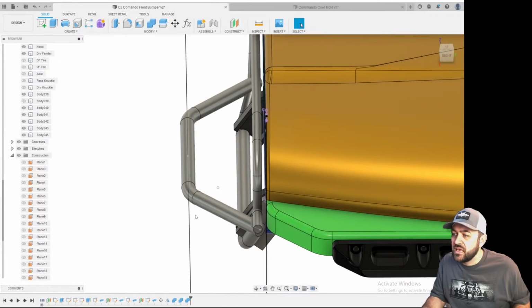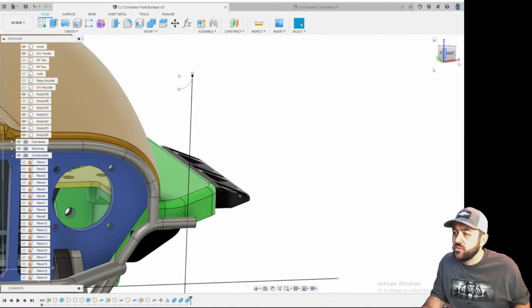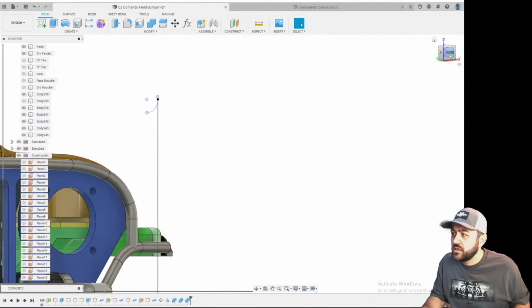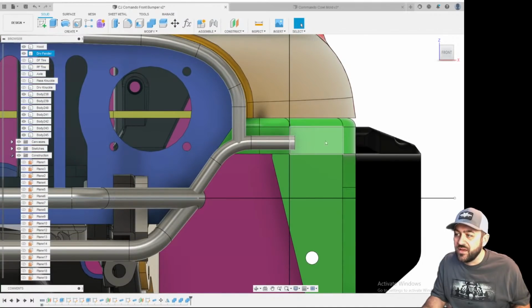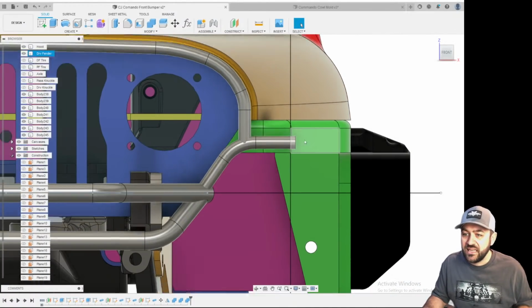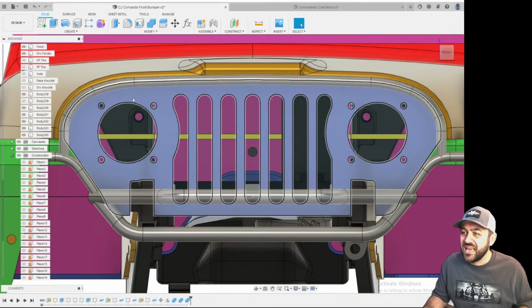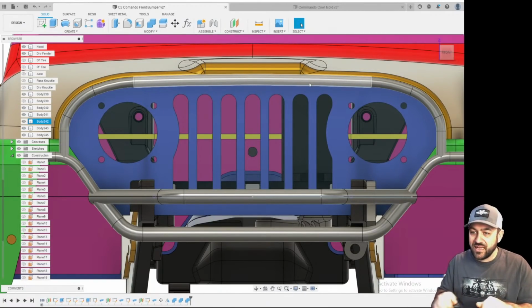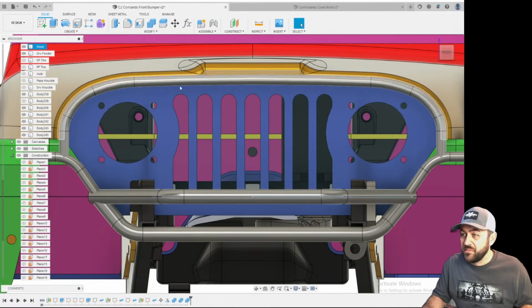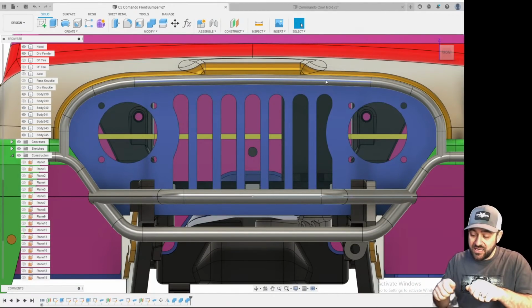Now, this should get me enough coverage of the front. It'll give me enough coverage width-wise for the rules there. This one will also end up long, and I can trim it to need. Let's see, the top piece is 2 different radii with no straight. Yeah, but that's only 1/8" rod. That stuff will be easy to just work by hand over a small die. I'm not too worried about that. Or I can 3D print myself a bend template and I can just keep bending and matching to it.